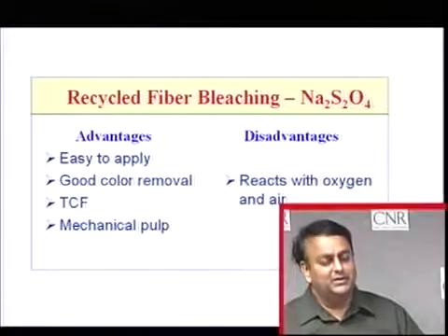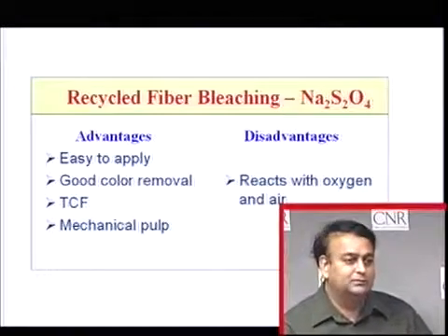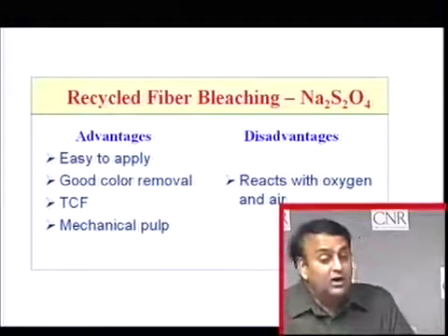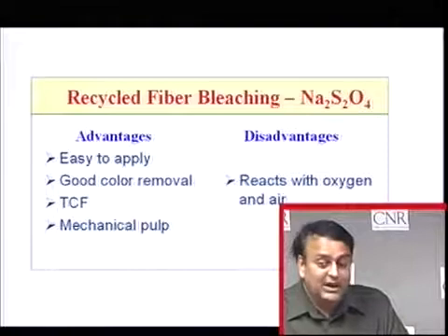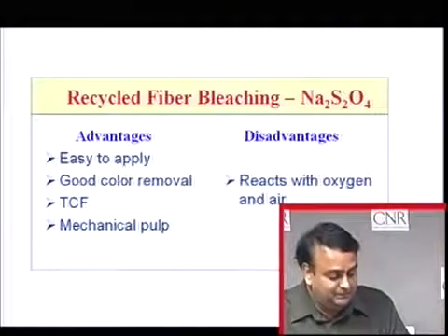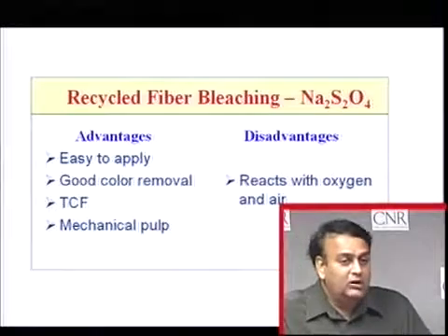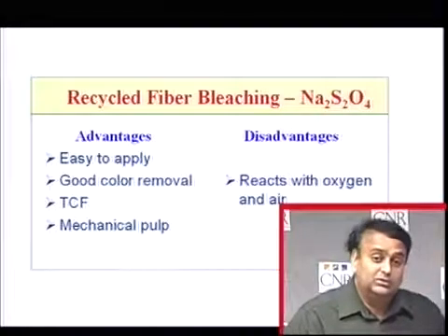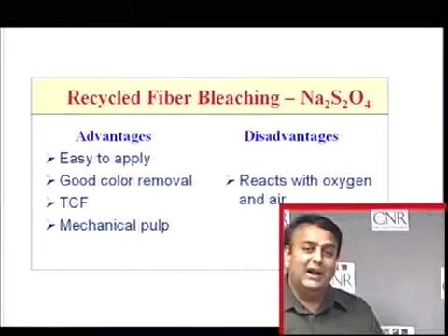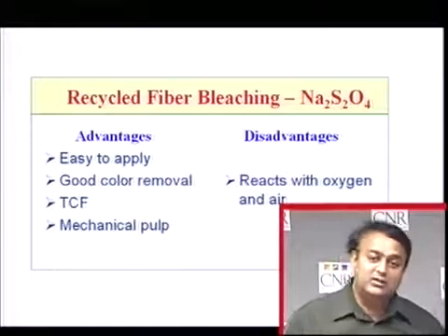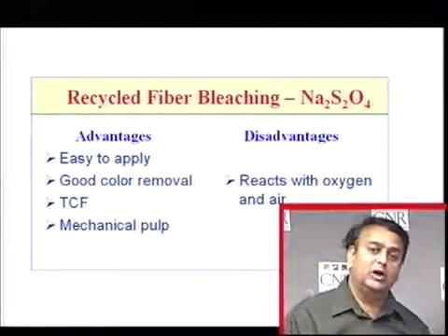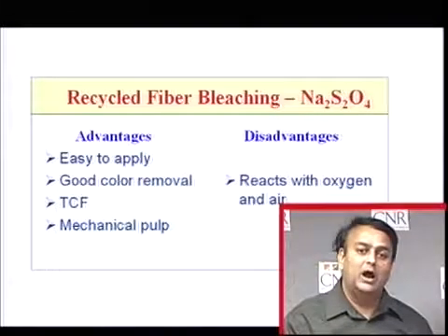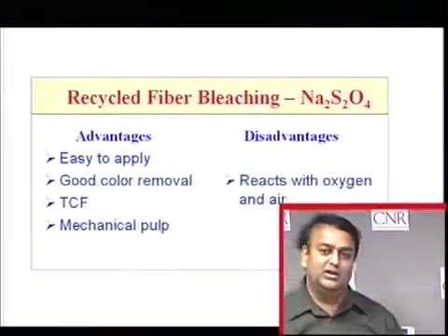What are the advantages of hydrosulfite? Very easy to apply. It's in liquid form, you just pump it and it goes into your system. Very good color removal. Some of the dyes are completely removed to make the pulp white. And total chlorine free label. And it works on mechanical pulp. So if you recycle fiber, office waste contains, let's say, some amount of newsprint, hydrosulfite can attack the lignin and also the dyes. So it works on both. Decolorization takes place and brightening, the modification of the chromophore on the lignin, takes place.